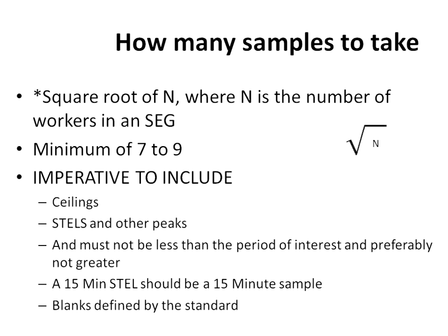You try to sample for the period in which the worker's absolutely exposed, so we try to get as close to 8 hours as we possibly can. STELs cannot be less than 15 minutes, but they can be greater than 15 minutes, but they should be as close to 15 minutes as possible, as well as overly sampling. And what I mean by overtly sampling. So can you sample for too long? It's preferable that you don't sample for longer than an 8-hour period. Although if your STEL goes over, that isn't quite as bad as your overall sampling plan going over. You try to get as close to that 8 hours as you can.